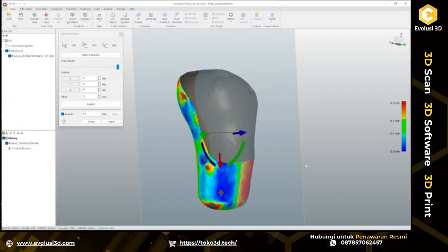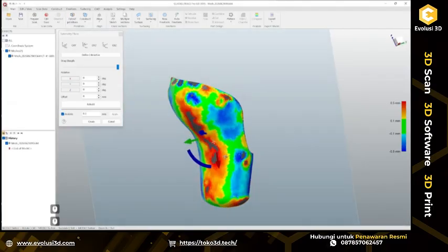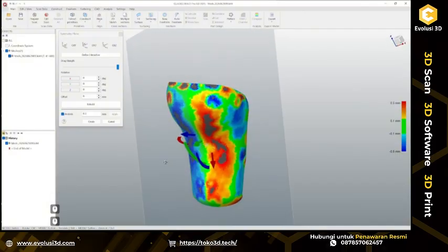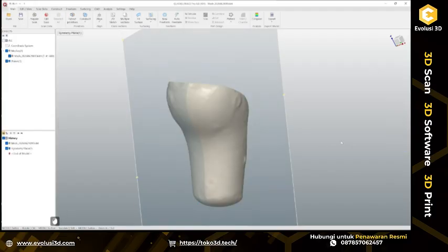Of course, it's not critical, it's like 0.5 millimeters, but first of all, considering this is a shift knob, it may be worn or something. It's not from a new car, so based on the idea that this part is like 20 years old, it might have its own deflections, warpings, and wear marks all around it. Okay, so I assume this symmetry plane is good enough for me.